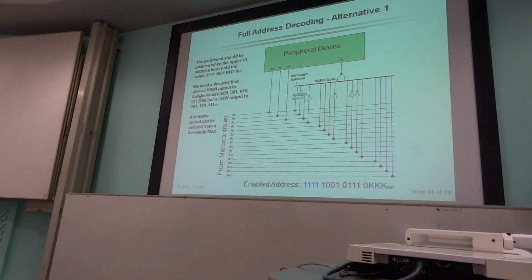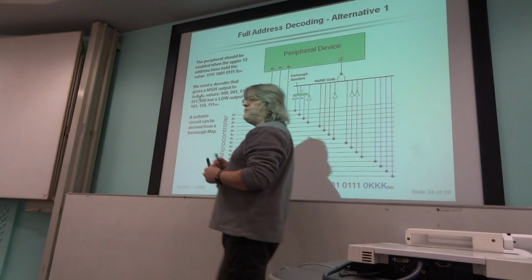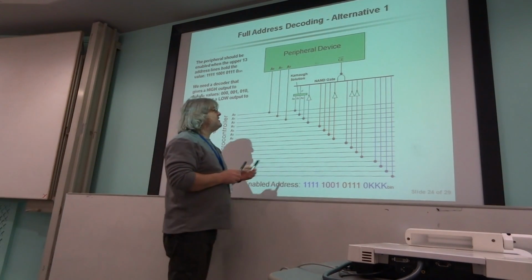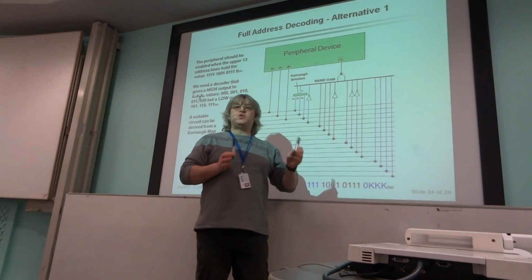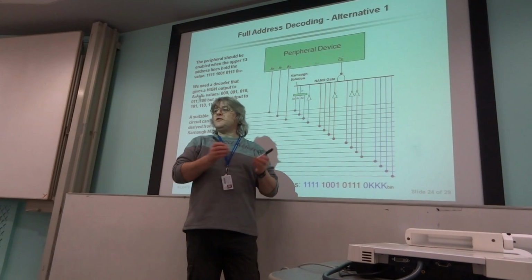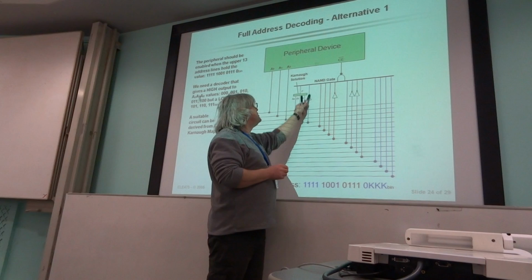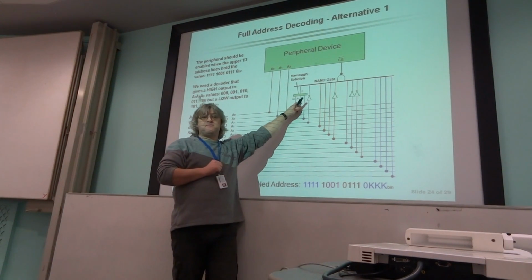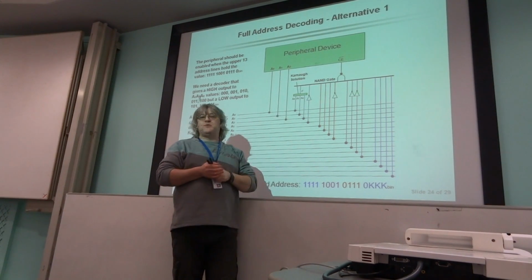An alternative way is, if you look at those 5 previous slides, you'll notice that 12 of the 16 inputs didn't change for all the 5 different combinations. The only changes were in the lowest 3 bits on the address bus. Well, we can use that to our advantage.